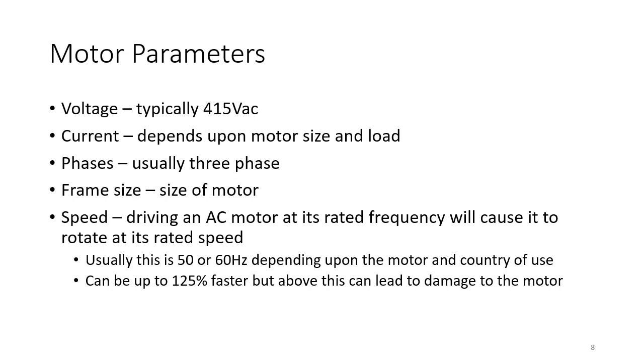Now, there are other motor factors that might be important. Of course, there might be cost, there might be weight, which are important when we're purchasing the motor and moving the motor. But in terms of control parameters, voltage, current and speed are often the important ones. Phases, of course, normally it's 3-phase, so we don't have to worry about that too much. We might also worry about kilowatts. Kilowatts is related to voltage and current and can be used to size the motor. Smaller motors might be in watts, but typically it's more the current we're concerned about. Voltage is normally the same, normally 3 phases, so it's the variable current which describes what we need to do in terms of controlling that motor with our control equipment.